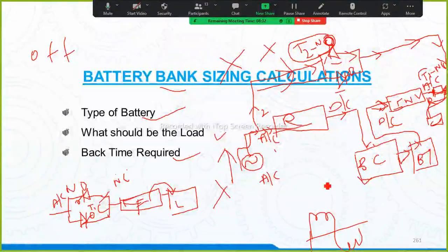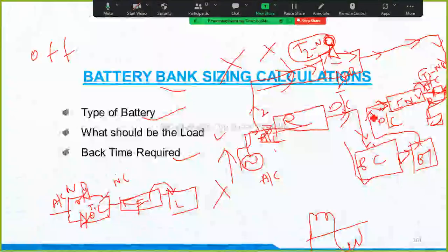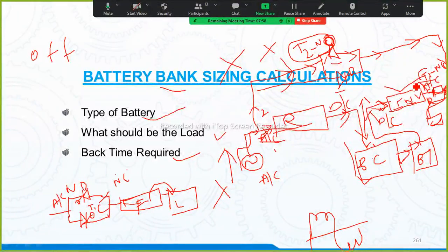So now what happens, you see here, when the power is there, first it will go through path 1, the rectifier which converts AC to DC. Battery is getting charged simultaneously. The battery power is going to the load through the inverter. Okay, then again converts DC to AC. Then again we have this filter. Then again to the load we are giving. So when main power is on, the power is going through path 1. Battery is getting charged simultaneously, and the power is going to the load.